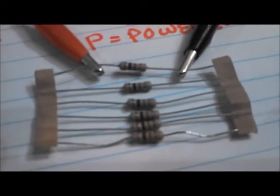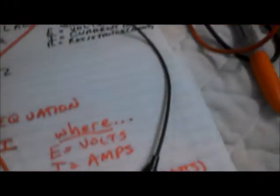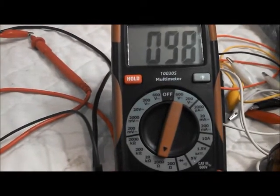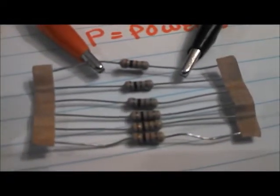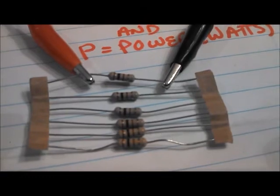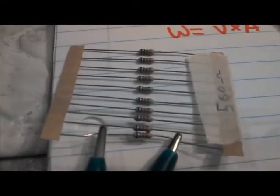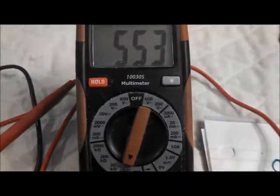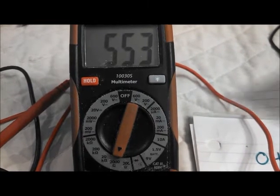This one, the brown, black, brown, should be reading 100 ohms. If I follow that all the way up to this meter, it's reading 98 ohms on a 2000 ohm setting. So think of that as nearly 100 ohms with a thicker amount of wall keeping the resistor from burning up. So this one is 560 ohms, again, on the 2000 setting, reading 553 ohms. We're going to do some experiments with these and see what happens.